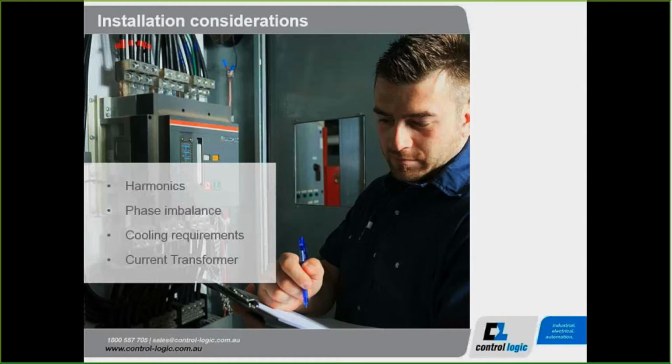fixing that. The reason is the power factor correction unit is actually a three-phase unit. So when it's correcting power factor, it's applying the same amount of correction to all three phases. So if your phases are quite imbalanced, by more than plus or minus 5%, adding power factor correction in could send one of those phases leading, for example, which obviously you don't want to do.